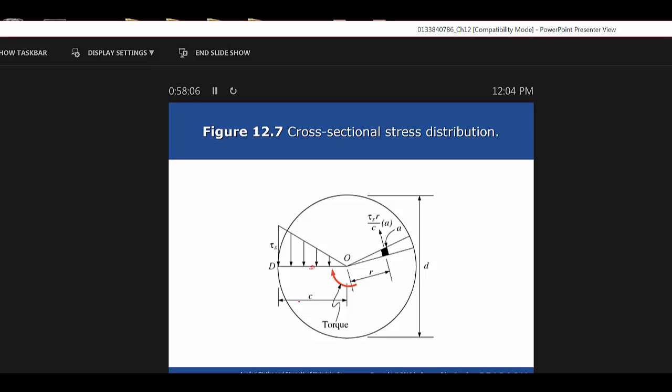Now note down there in that table 12.2, there's typical increments that you can buy if you buy the shaft material that you're dealing with. So for a half inch up to 2.5 inches, they're saying you'll be able to buy that in increments of 1/16 of an inch. When you go to 2 5/8 to 4, then you're not going to get them in 1/16 of an inch. You're going to get them in 1/8 of an inch. So what you would have to do is, if you had calculated, let's say you calculated the diameter at